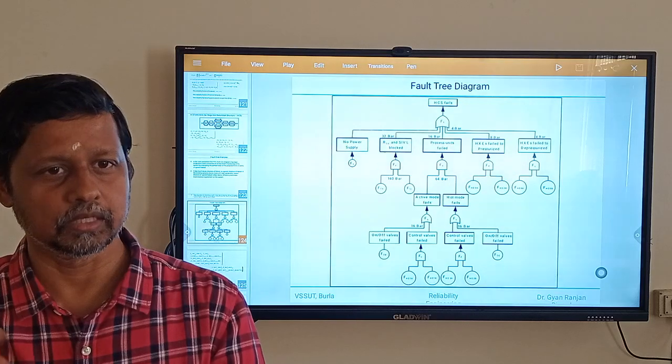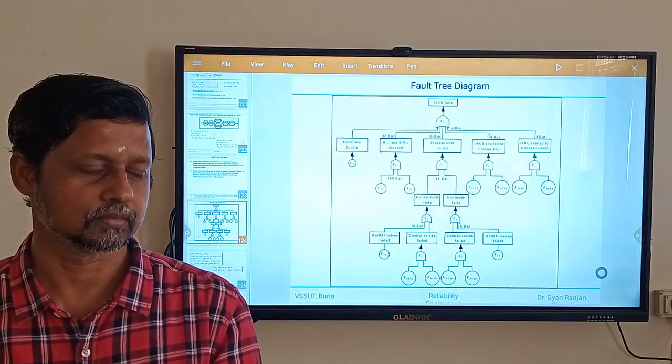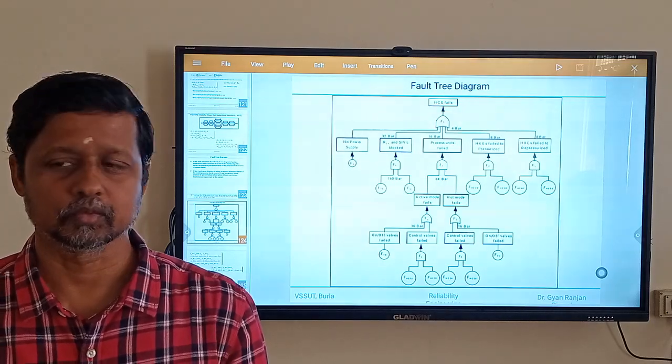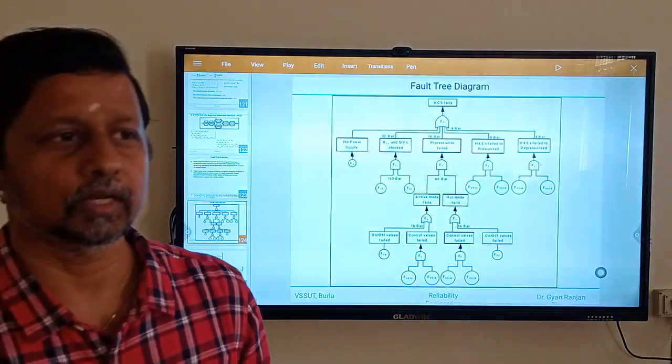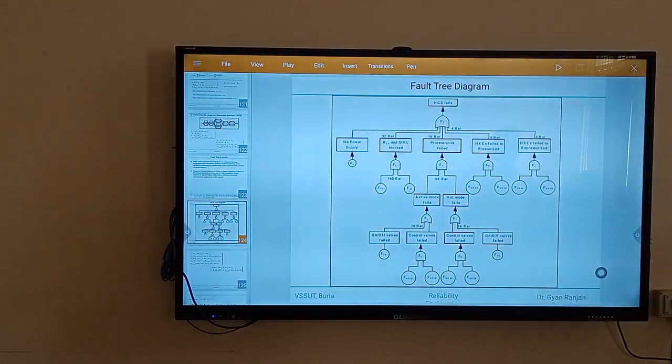Then again you have to invest some heat, brother, it became a little warm. So that is a very poor design, that you are using power to generate power. Okay, you are using some fuel to generate power, understood, but you are using power to generate power, that's not a good idea. So chilled water means roughly very cool, roughly around, let's say the maximum is around 7, okay? 5 to 7 degrees Celsius.